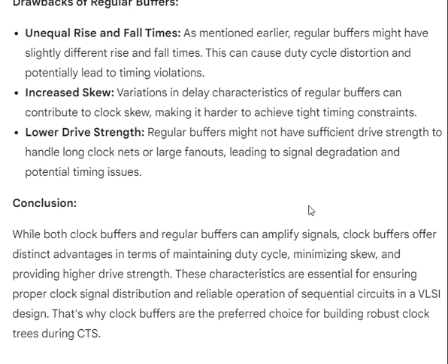Conclusion. While both clock buffers and regular buffers can amplify signals, clock buffers offer distinct advantages in terms of maintaining duty cycle, minimizing skew, and providing higher drive strength. These characteristics are essential for ensuring proper clock signal distribution and reliable operation of sequential circuits in a VLSI design. That's why clock buffers are the preferred choice for building robust clock trees during CTS.